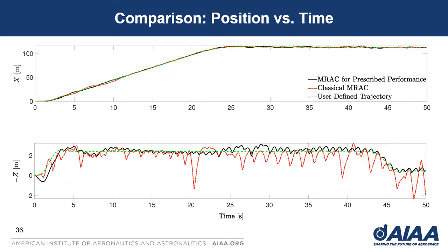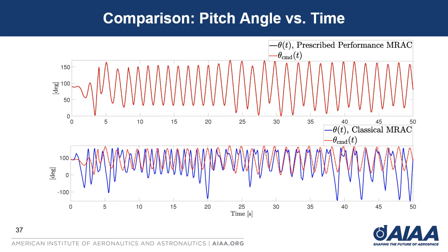On this slide, we showed the x and z position versus time in the top and bottom plots respectively. Clearly, the model reference adaptive control with prescribed performance outperforms classical MRAC in terms of tracking the user-defined trajectory. Here we show the pitch angle versus time for prescribed performance MRAC and classical MRAC.